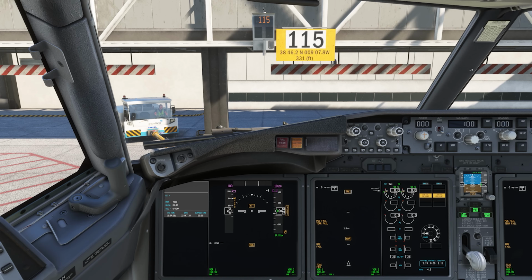Next we'll briefly discuss here on the ground the autopilot and the flight control computer. Again, it works very similar to the NG, but there have been some enhancements. For example, if the stick shaker activates, the autopilot automatically disengages, so you can complete the stall recovery as well. The flight director bars will then be removed in that instance. These are things I hope to demonstrate in the future in a flight tutorial of some sort as well. And there's an inhibited autopilot nose-up trim when the airspeed is within the amber bar, the minimum manoeuvre speed.